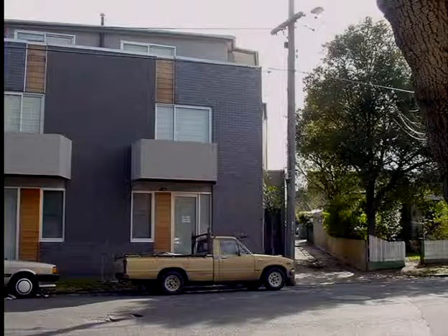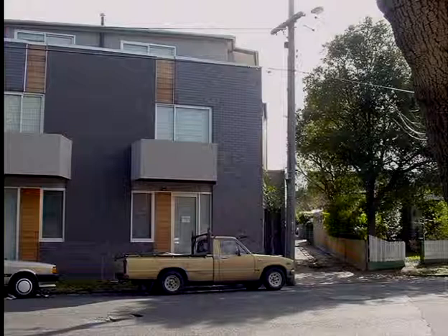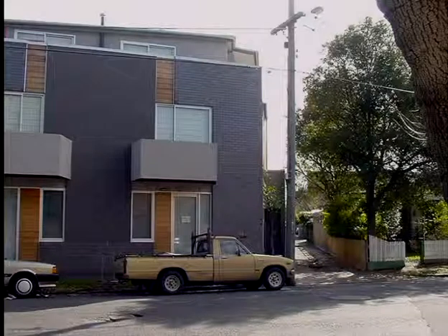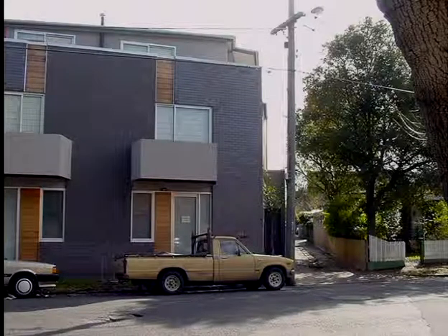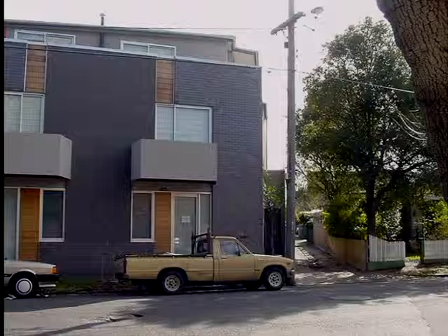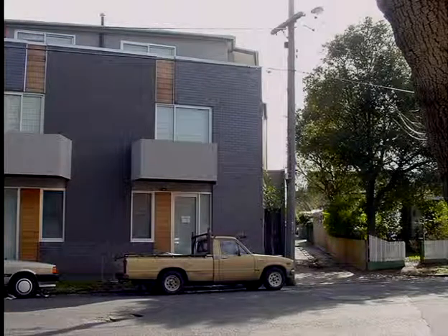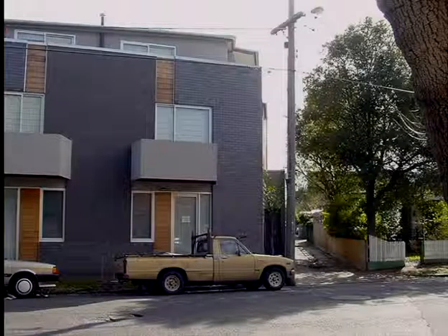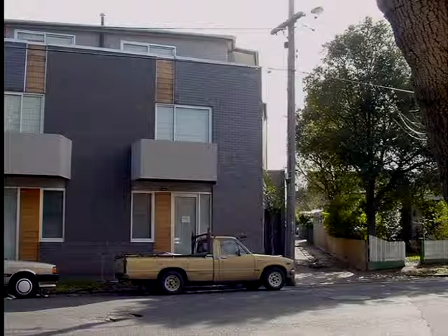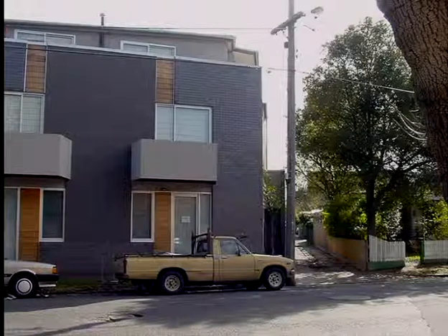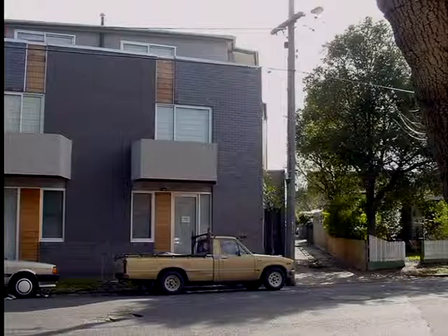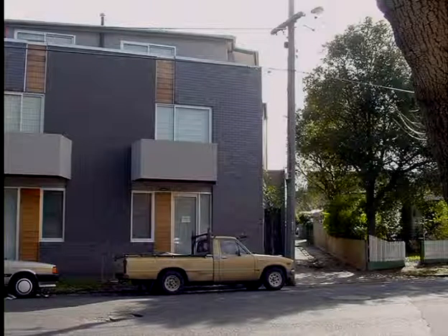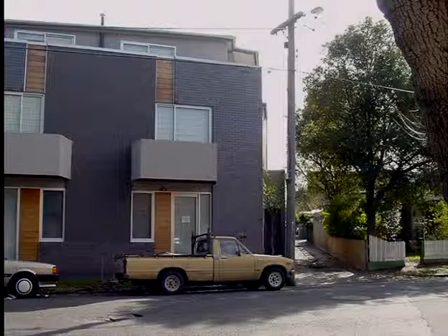Because in high winds, the cable will move. And the point it'll move the most is in the middle between the two poles. Now, what can potentially happen is that if that power line comes too close to metal, it'll arc. And it'll electrify the building. It'll arc onto the building. So there's very stringent requirements, as you have to be a certain distance away from power lines.